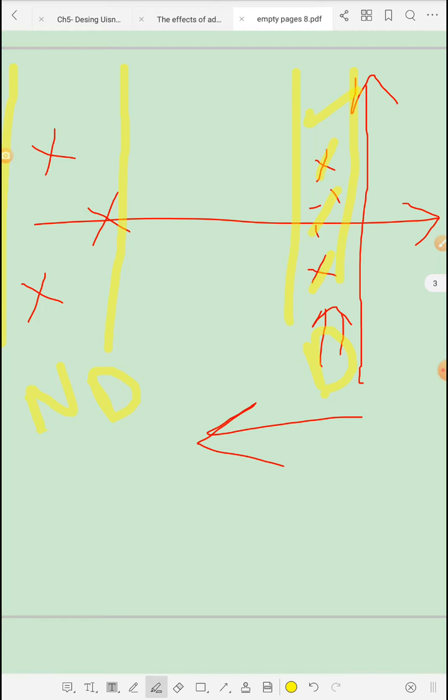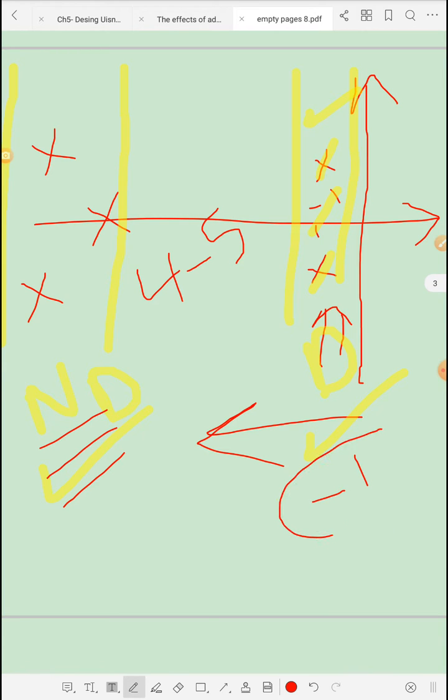In order for those poles to be dominant with respect to the rest of poles which are non-dominant, the real part of the dominant, assuming in this example it's -1, okay, those non-dominant closed loop poles should be at least 4 to 5 times larger in real part than the real part of the dominant closed loop poles.